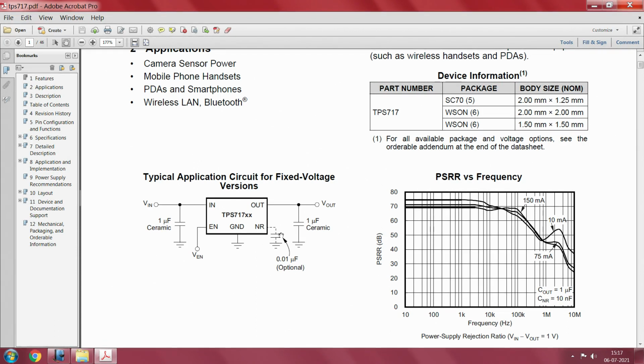If you put this value you will get another characteristic which clearly indicates that the performance that you are looking for is available here. In order to get to that performance you will have to look at what values he has chosen and accordingly populate your LDO with those values. This is why you need the data sheet, otherwise you can't design the power supply block for an IoT system.